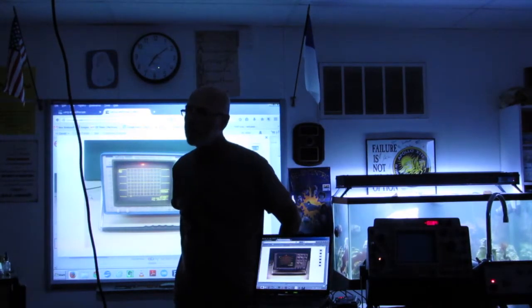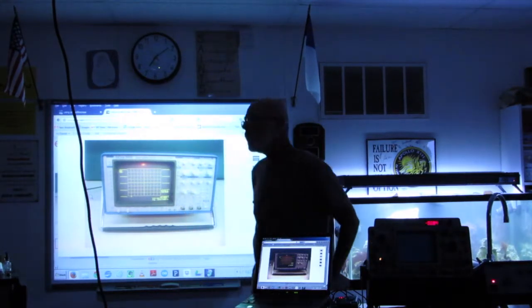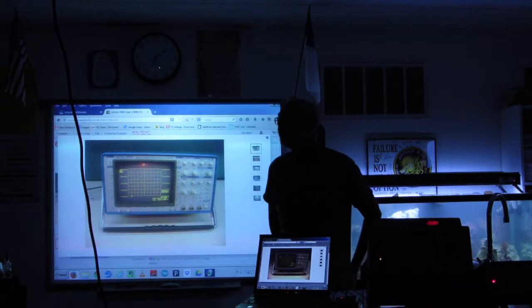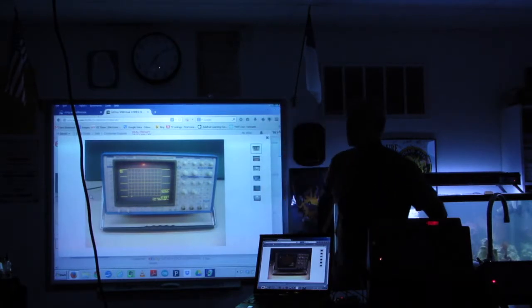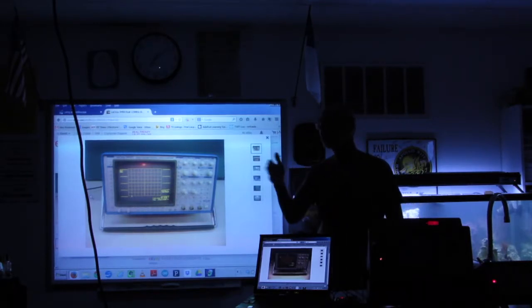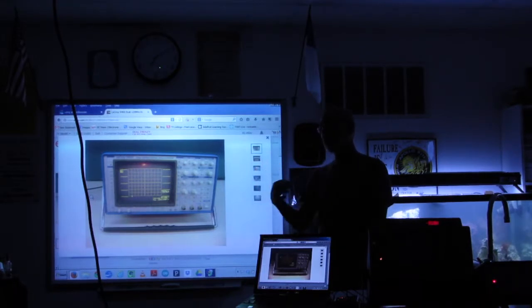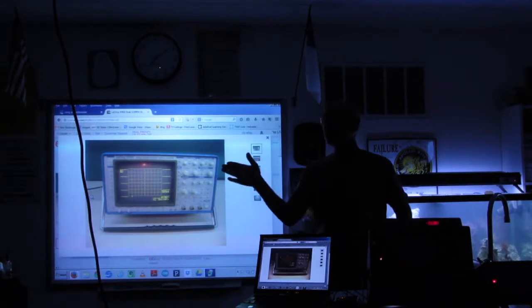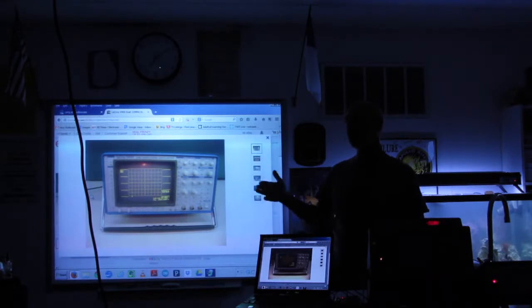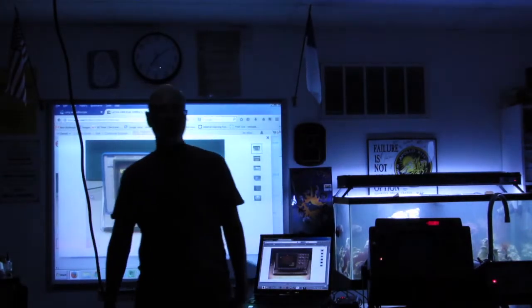Is this in the same family as a seismograph, where the needle Yeah, actually it is. A seismograph is a mechanical oscilloscope. When the paper flows through, that's your time. And when the seismograph needle wiggles, that's simply your input voltage going to an amplifier and activating two electromagnets that make a mechanical needle move, and that's your vertical axis right there. That's your input channel. Good analogy. Yeah, good question.